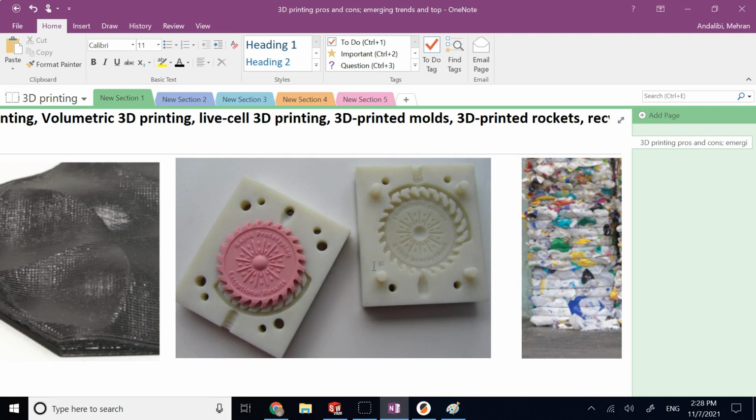Plus their melting temperature is way higher than the plastic that is going inside them. So they are absolutely suitable for injection molding. But the fact is, making these molds out of metal and CNC machining them is the big cost and a large portion of the cost of injection molding. Molds are very expensive to make.